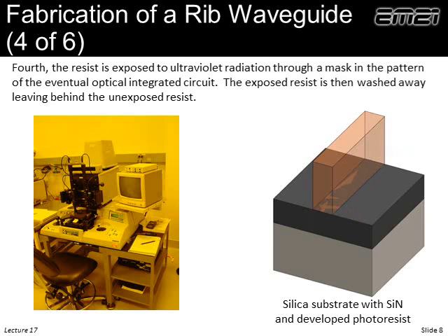and it's right on top of the silicon nitride layer. So what our next step will do, we'll etch. And in fact, etching is bombarding this with a bunch of particles very fast. So in fact, the resist will etch away too, in addition to the silicon nitride. However, before the resist is gone, it's protecting the center region of the silicon nitride temporarily.